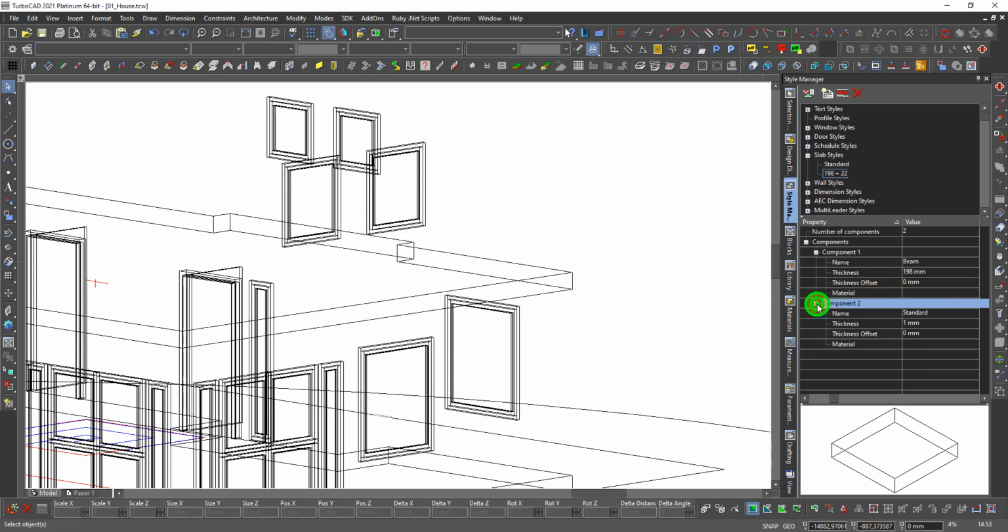And then component 2 is chipboard. Sponplate in Norwegian, but I hope I'm correct. Chipboard, and that plate is 22 millimeter. You see it come down here, but it should be standing on top of the beam, so it has an offset of 198.